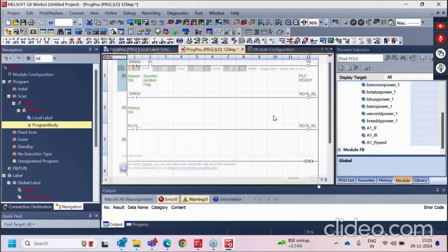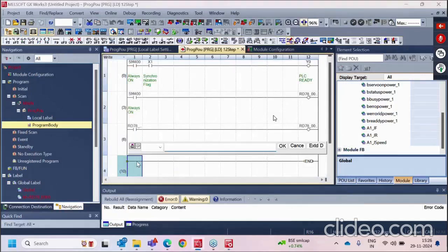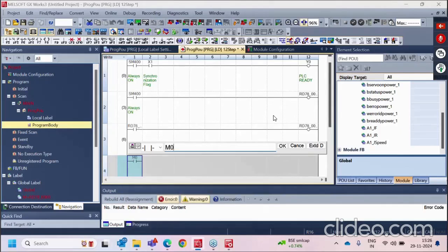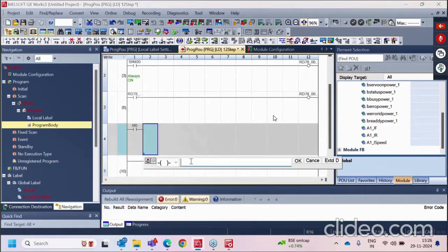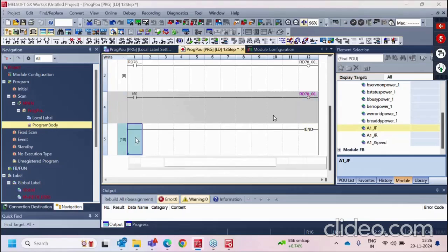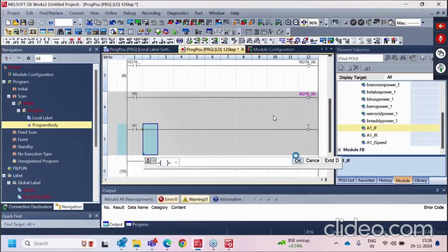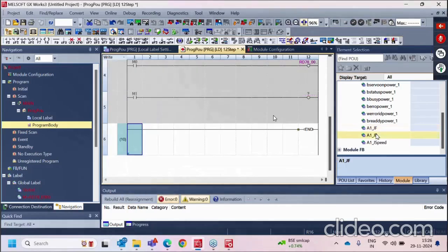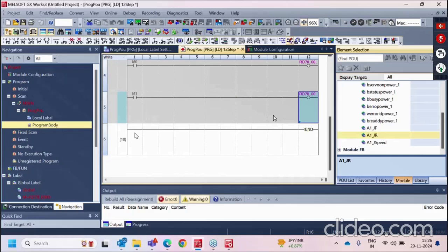Editors. So on the other side, in the PLC side in GX Works 3, we have to write a program for the jogging by using those forward and reverse labels. So I am just using an internal bit and as an output I am using the axis 1 label. This is the axis 1 jog operation label I am using. Here I am using M1 output, make it okay. And this is the jog forward label we are using.